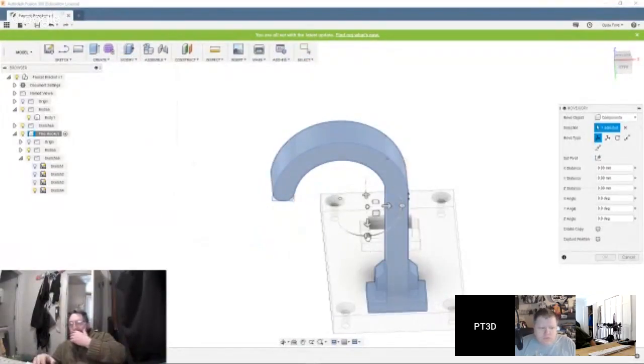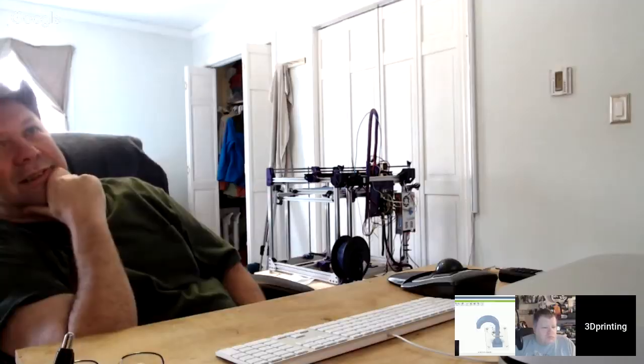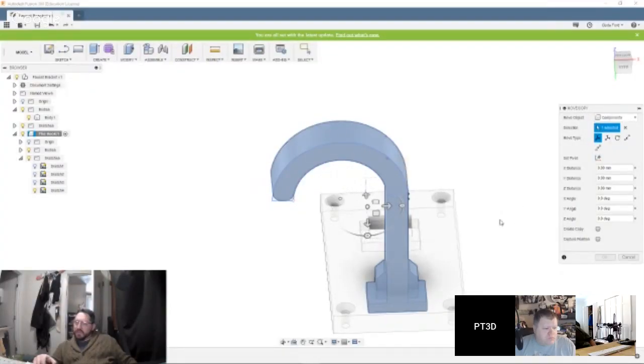Now, the one thing you want to do is relocate your center. You want to bring the center down to the plate, not in the center of the center, if that makes sense. Your pivot point. Okay, well, how do I do that? You've got to click your pivot point. One of those is relocate pivot point or change pivot point.